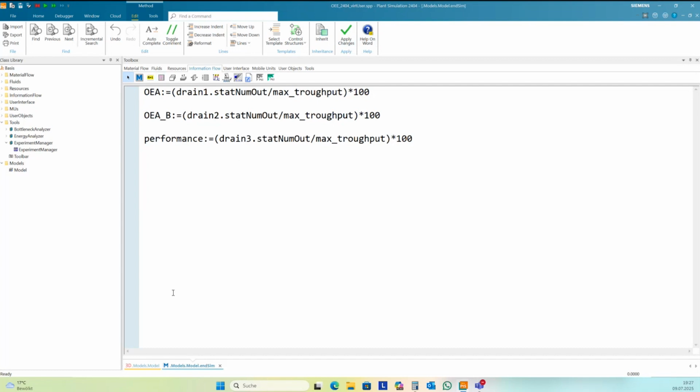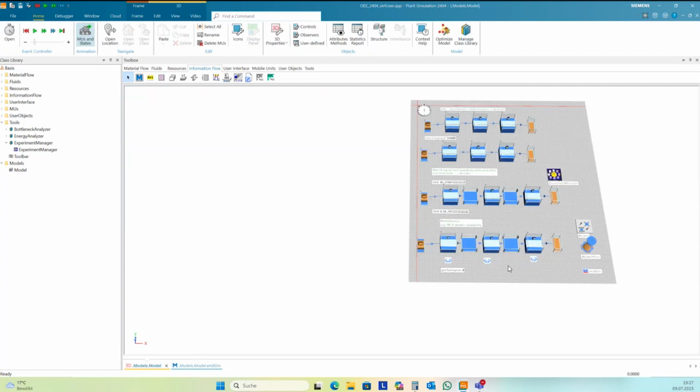What does it mean if you have only a 98% availability for the workers and we have some buffers in between? The buffers work in the same way as the availability. If one worker is at the washroom and there are still some parts available in front of the other machine, then it can run until the buffer is empty. Another way to increase the performance would be to work with floaters. Then another worker comes when one worker needs to go to a break or wants to smoke a cigarette and so on. Okay, let's have a look.